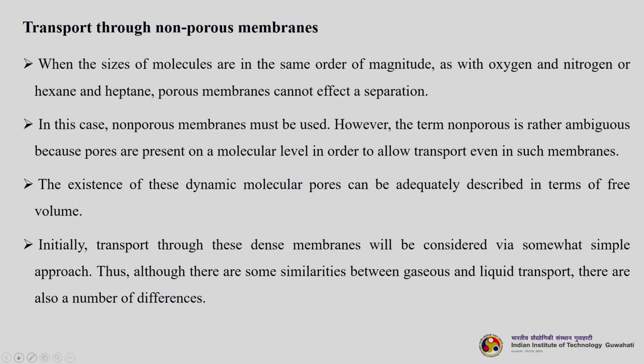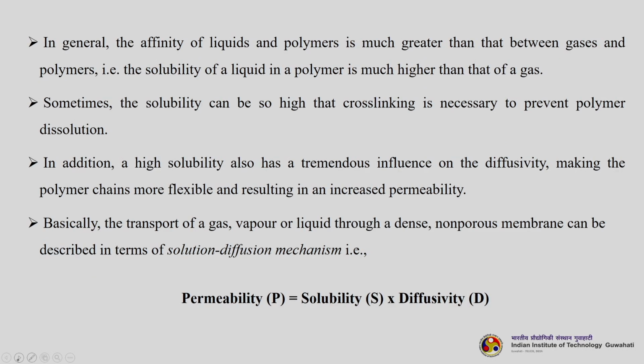Initially, transport through these dense membranes will be considered via a somewhat simple approach. Although there are some similarities between gaseous and liquid transport, there are also a number of differences. In general, the affinity between liquids and polymers is much greater than between gases and polymers, that is, the solubility of a liquid in a polymer is much higher than that of a gas. Sometimes the solubility can be so high that cross linking is necessary to prevent polymer dissolution. In addition, a high solubility also has a tremendous influence on the diffusivity, making the polymer chains more flexible and resulting in an increased permeability.